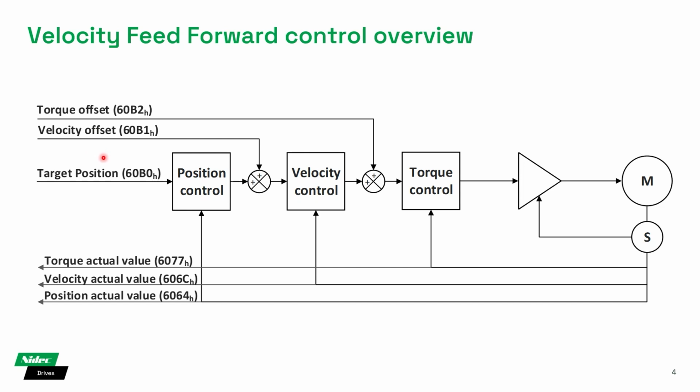So in this scenario, we enable the velocity feed forward system in CSP modes, that's cyclic synchronous position mode, which is what's used with Beckhoff TwinCAT NC axis. And instead of calculating it by differentiating from the target position, what we do instead is we feed forward directly from the profile generator in the NC axis the velocity feed forward reference and inject it into the control system.